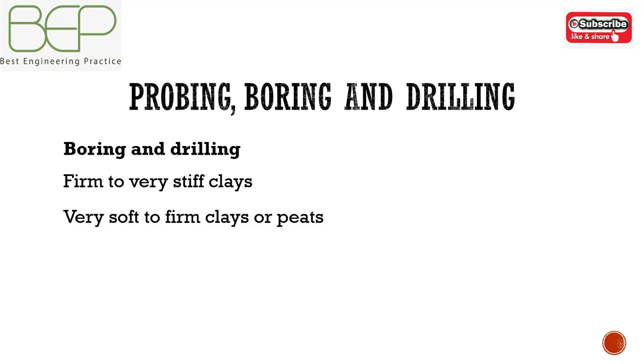Very soft to firm clays or peat. Thin wall piston drive samples may be taken at 1 to 1.5 meters, if laboratory tests are required, or alternatively in-situ vane tests can be carried out to obtain undrained shear strength.